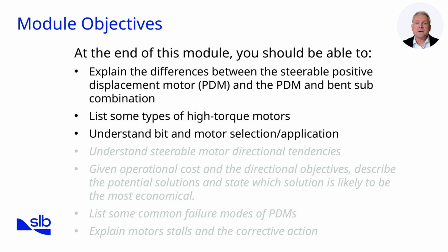Finally, we will link motor design and performance to bit selection, understanding how different bit profiles and aggressiveness affect tool face control, weight transfer, and vibration management. These objectives will prepare you to apply PDM principles effectively in planning and execution.